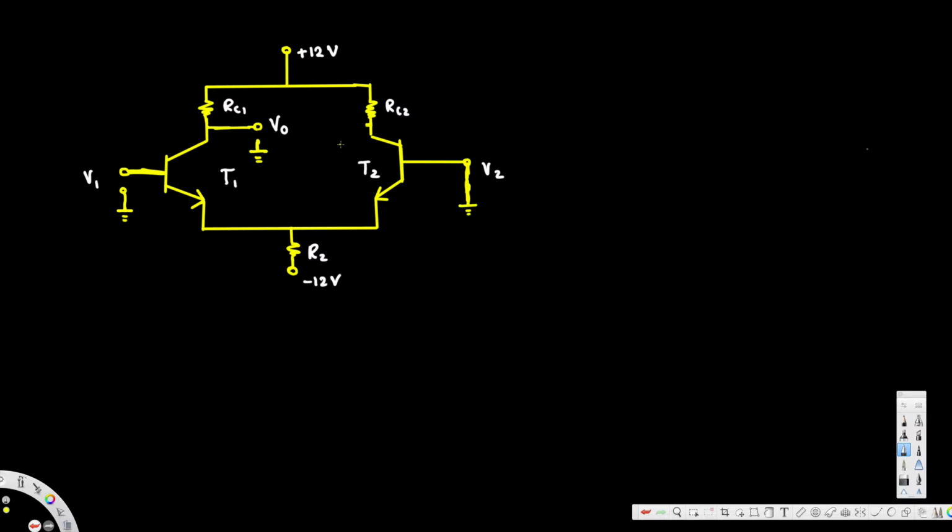And if you have this one grounded and this one short circuited, and also the output like this, this is called single-ended input and double-ended output. Those are the four types of differential amplifiers we have to know. Now let's label these. The commonly used one is the double-ended input and single-ended output.